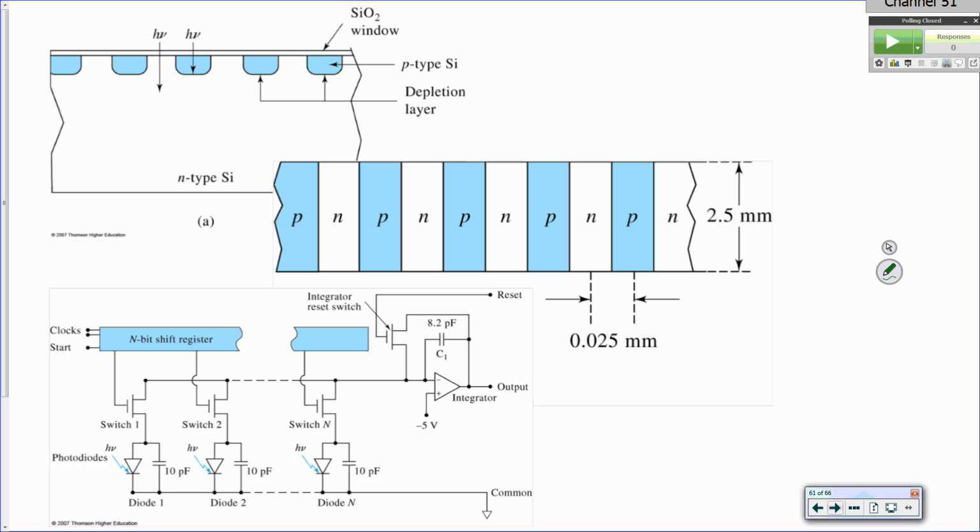So the instrument itself with the photodiode array was this big, and all the stuff trying to get the information into the computer was huge, because every one of these took its own circuitry in terms of an amplifier. It would trap the charge from the diode with a capacitor, and then flip the switch, and it would integrate how much charge was in that capacitor and give you a signal out of it. So every one of these places where light would come in, it would be trapped in this diode.